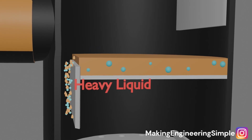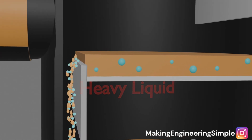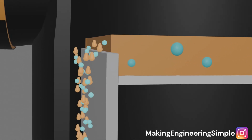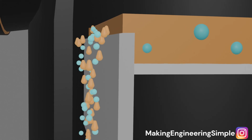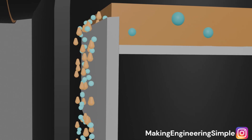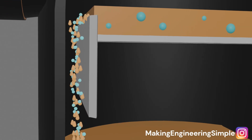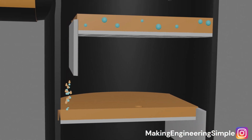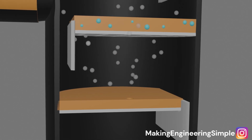As the liquid travels, a small metal lip called a weir forces it to pool up on the tray. Once the liquid gets high enough, it overflows and falls down the downcomer, continuing its journey to the next plate. Pooling the liquid like this does something critical. It increases its residence time. This slowdown gives the rising vapor time to punch through the liquid.